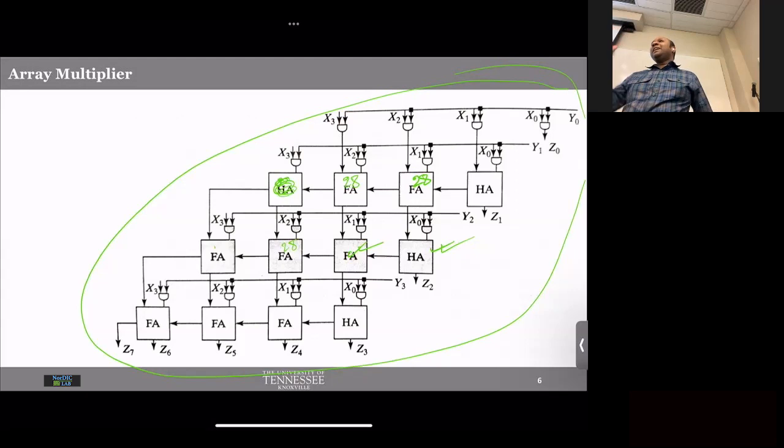Can you appreciate how many transistors and how complicated this system will eventually be? That's kind of indicating VLSI, very large scale. It starts getting more complicated very quickly. And this is a simple multiplier. I mean, just imagine what you will have to do for graphics design or something. Makes sense? But you don't have to start from scratch. You see, everything you build somehow links to your CMOS inverter. Imagine that's where it all began. You started designing an inverter and then you started designing logic gates using the exact same principle as a CMOS inverter. Pull up network, pull down network. In the end, that's all that's happening underneath.